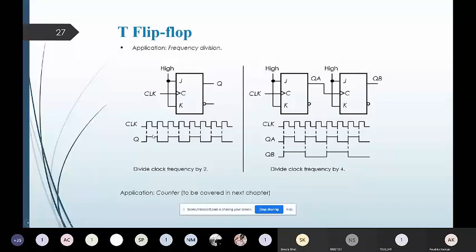So here in this waveform representation, you can see that the clock is a positive edge triggered clock. At that clock, I find that the Q has changed, as this particular flip-flop is a positive edge triggered flip-flop, and that flip-flop is in set mode.